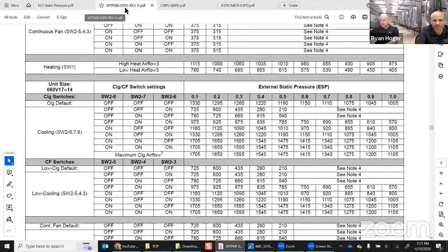That's a dual port manometer, which is nice because then you can measure that supply static and the return side static at the same time. You do have to do the math to add them together. I know that's unpleasant for people. Math is not your friend usually. But you have a cell phone.